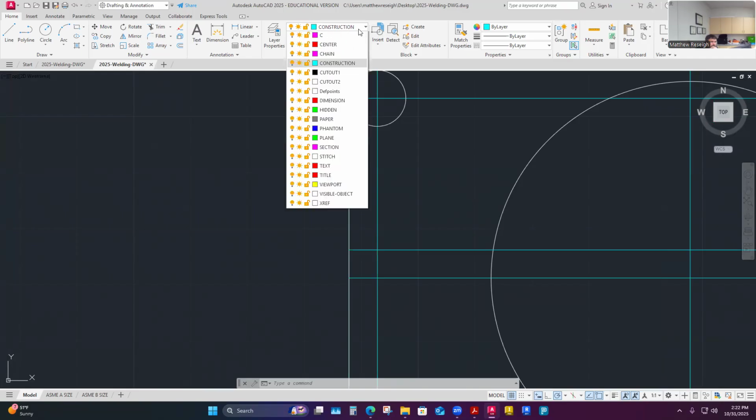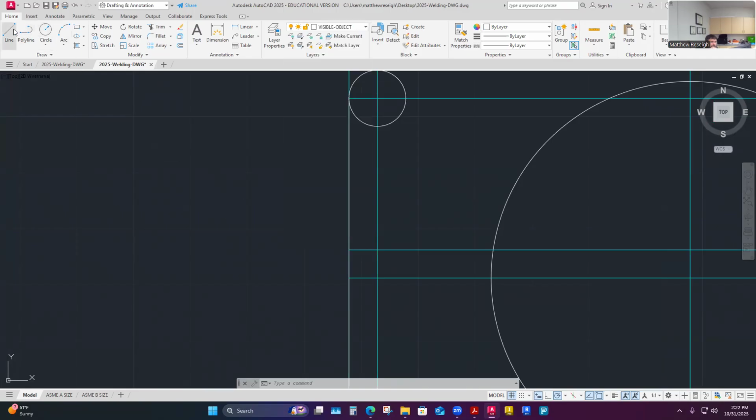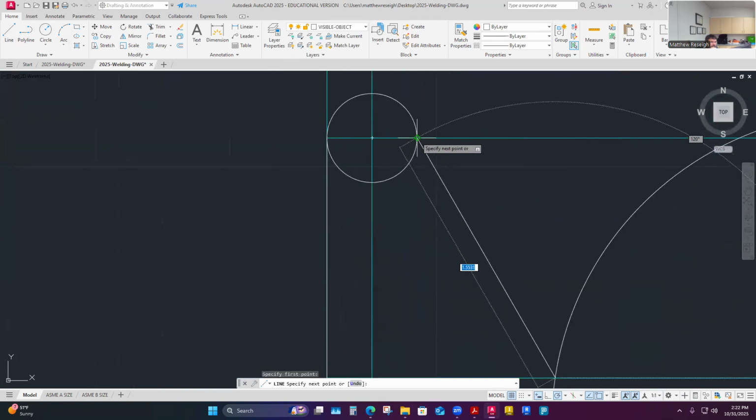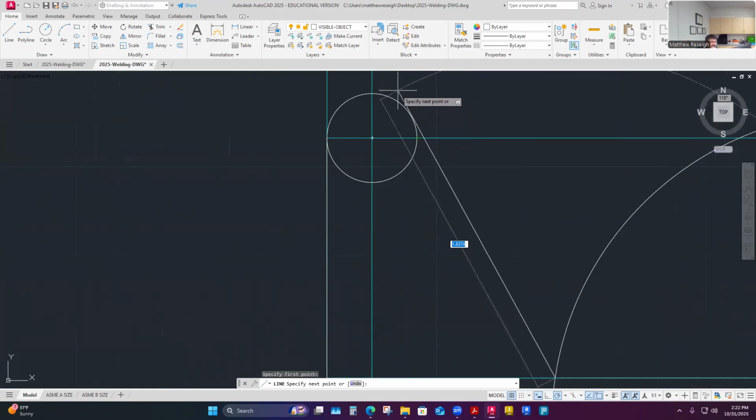I'm going to go to my visible line work, pick that command. That's the point. And then I'm just going to come over here. I can hit the quadrant. Yes, that's not exactly right. I want it to be tangent. There, the tangent shows up. And no matter where, even if I'm like this, tangent it is, it's going to snap to that